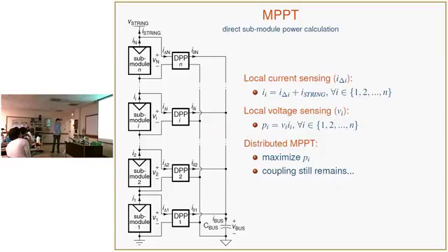Each of these DPPs is a power converter, so they have input and output capacitors. I should have said that I was just showing this bus capacitance explicitly, and that basically represents the aggregate of all of the output capacitors. All of these DPPs need to be connected to that bus somehow, and it's through conductors. That's a drawback for this topology: you need extra conducting cables for that.